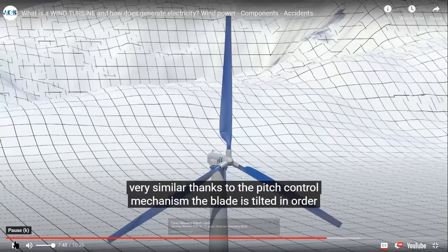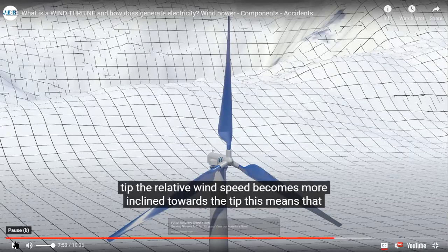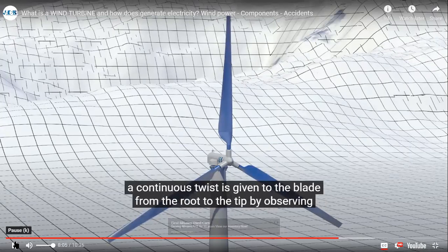Thanks to the pitch control mechanism, the blade is tilted in order to be always aligned with the airflow. When the blade speed is increased to the tip, the relative wind speed becomes more inclined towards the tip. This means that a continuous twist is given to the blade from the root to the tip.